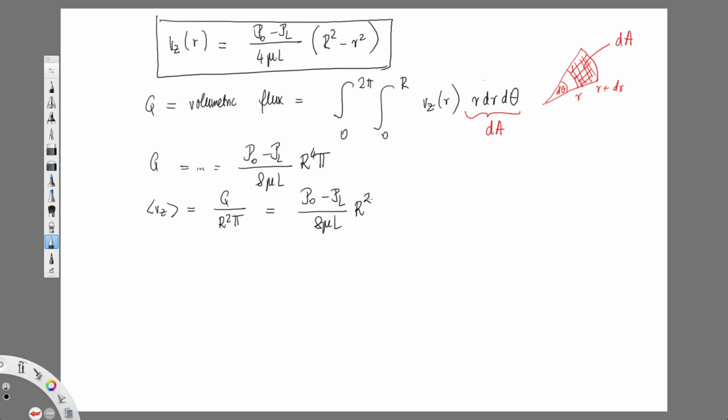My equation in terms of phi, the one that is minus d phi zz dz, minus 1 over r d(r phi rz) over dr, plus rho g equals 0, is for any kind of vertical case, okay? So that general equation is basically for any type of fluid, because until I actually show what phi is, I'm not specializing in any specific fluid.